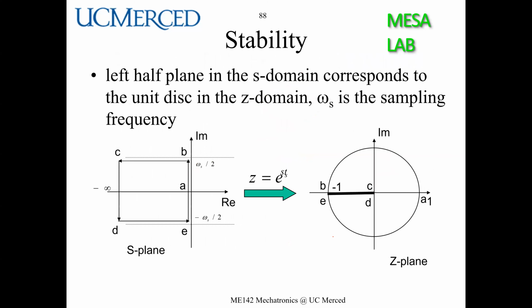But in the frequency domain, I'm going to show you that because s is a complex number, z is also a complex number. So in the complex plane, the left half plane is where your poles should be located such that the system is stable. But let's go through points A, B, C, D and check.